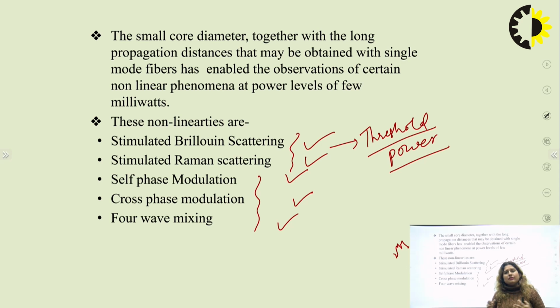So in this lecture, we have covered the dispersion and the major causes of dispersion, the different types of dispersion, and how dispersion can be compensated with the help of dispersion flattened fibers or compensating fibers. And lastly, we discussed the Kerr effect, that if you increase the intensity beyond some limit, there will be noise introduced in the fiber, and this noise will corrupt your data at the other end of the fiber.